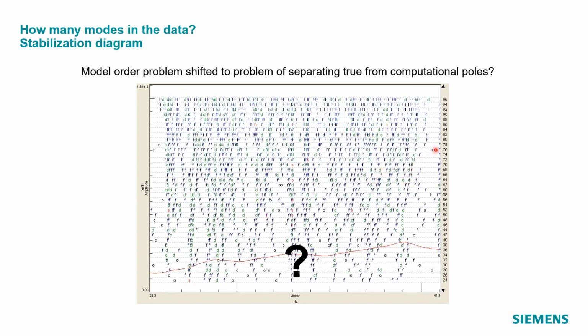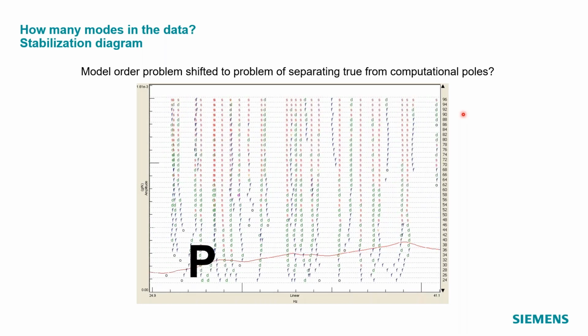And this is a slide I made already almost 15 years ago or even longer. It's at the moment we developed Polymax. So this was a stabilization diagram from our earlier methods, the time-domain method. If you use the same data with Polymax, you get already a much nicer stabilization diagram where you easily see the modes. This was quite challenging data. It was a heavily damped vehicle that we tested here.